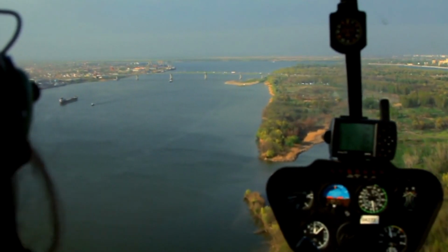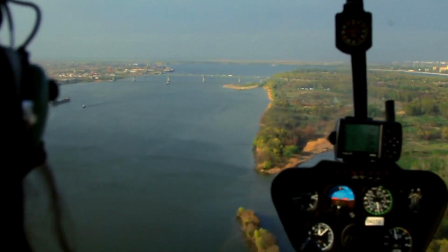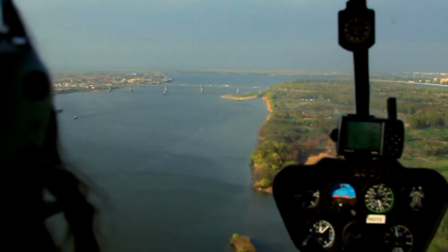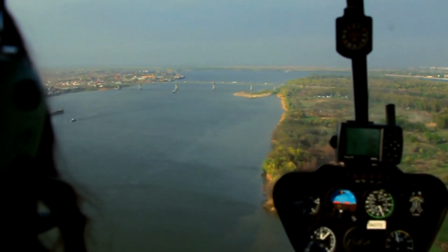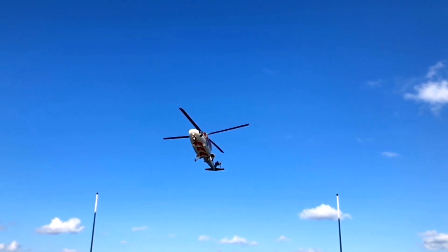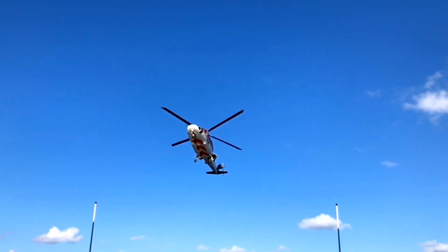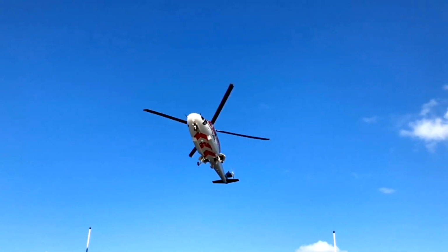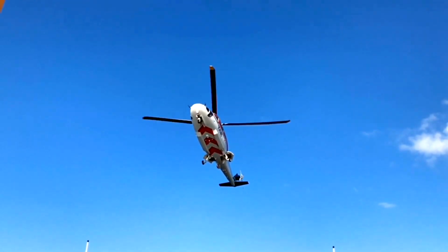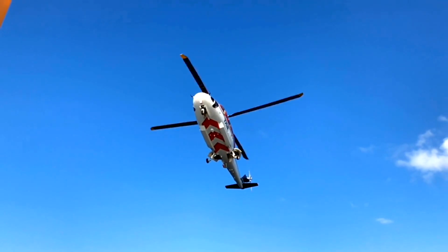As the maneuver begins, the pilot applies cyclic toward the desired side, gently returning it to neutral to maintain a controlled ground speed, no faster than a brisk walk. In this sideward waltz, the pilot orchestrates a symphony: constant ground speed and track with the cyclic, perpendicular heading to the ground track with the anti-torque pedals, constant altitude with the collective, and the perfect cadence with the throttle.